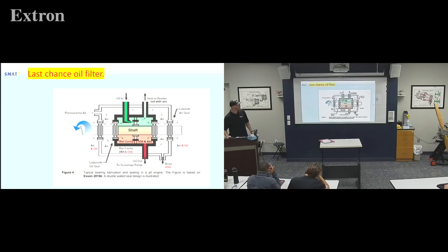All right, last chance oil filter. Not drawn in here, but JZ did a good job. When I thought last chance oil filter, in my head I was always kind of thinking there'd be a little screen in there, right? If you noticed from his video yesterday, it actually looked like a tap that you were going to tap metal with. And in a tap, you've got the little cutouts every 90 degrees. Basically, when he drew that and showed it to you, in between each cavity on each side of the thread tap, the oil would have to go through.